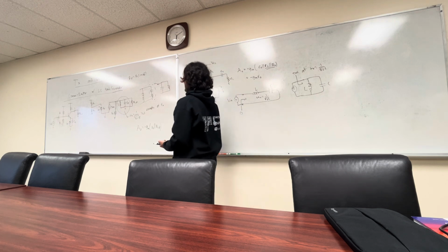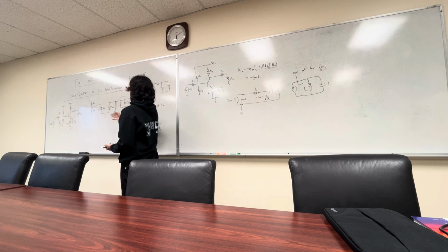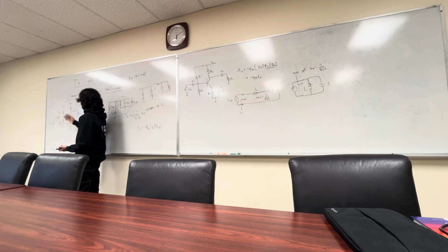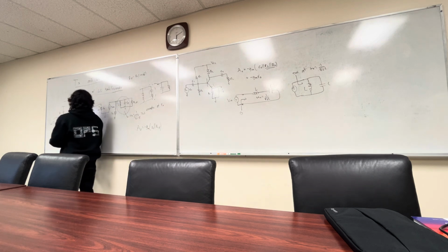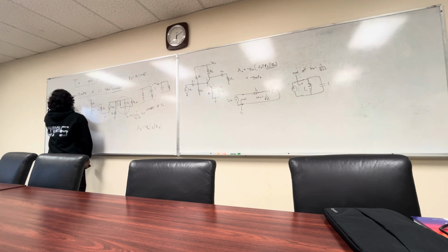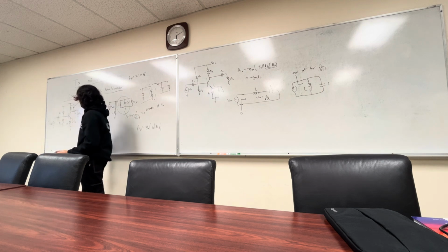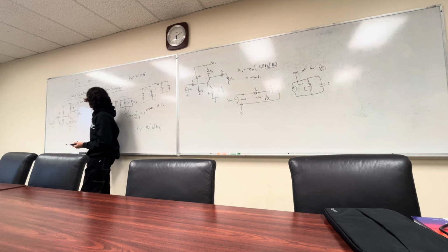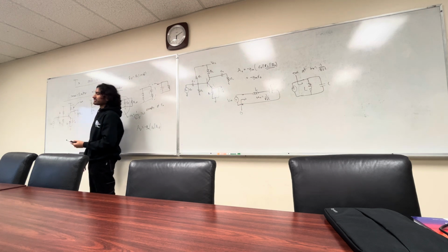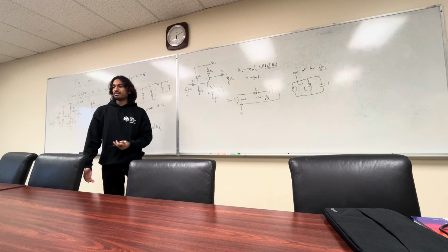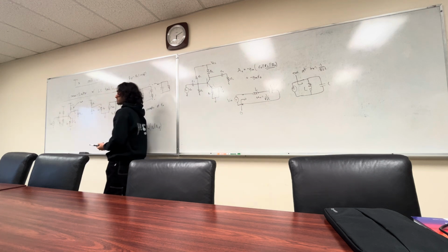Now let's take a step back and think, what happens here? This inductor is going to have some parasitic loss, but you can model that loss as a resistor in parallel here. We call it R para for now, R parasitic. I wouldn't even say it's parasitic, but it might be the best way to describe it. The idea is this inductor for DC will sustain no voltage drop across it.